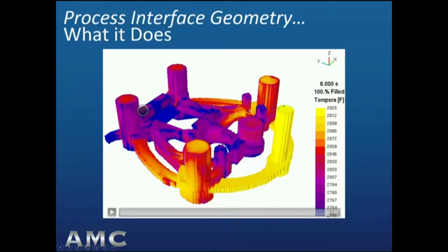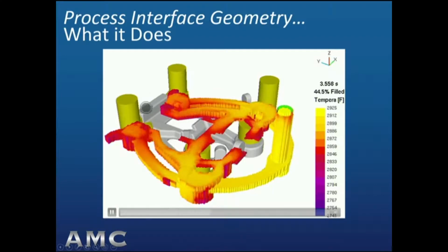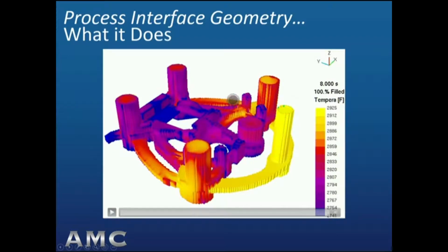But watch at the upper left and how quickly the blue forms from the chill that's underneath the mold cavity in the sand. The idea of gating primarily is to create the temperature distribution that favors the solidification gradients needed for the solidification integrity that results in the mechanical properties that are specified. The risering is attached to provide reservoirs of feed metal to feed solidification shrinkage inside the cavity, and essentially take the shrinkage that's occurring inside the cavity and transport it out of the casting and into the riser itself, where it can be cut off and remelted.